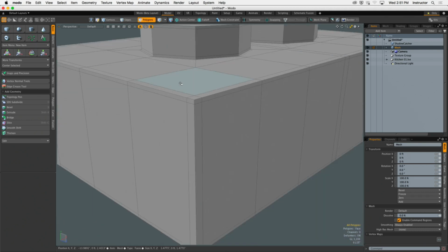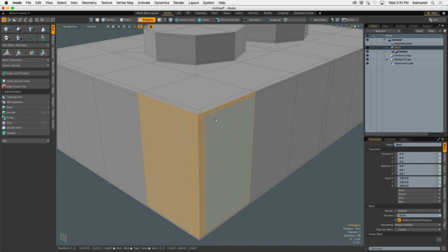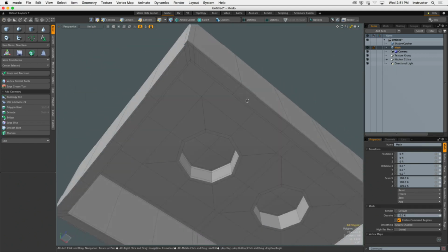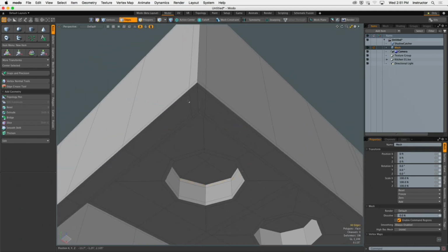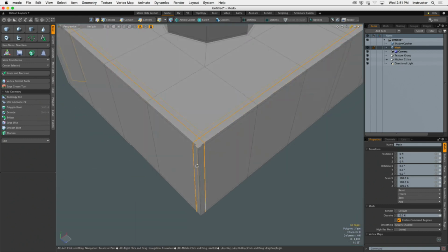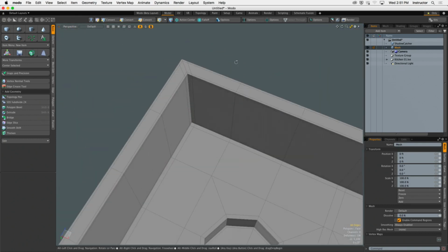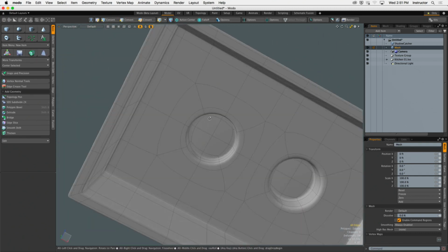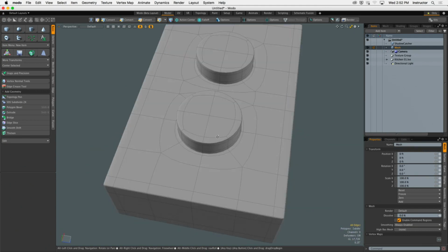Now, in the corners, I've done the exact same thing. If you think about it, I have a plane here that's transitioning to this plane over there. Well, I've added some edge loops to start locking in the algorithm and tighten everything up. And I repeat that pattern over and over again, even down into the insides. Now, in the corners, I get these cool little diagonal jobbers, which is just fine. I'm just using the loop slice for almost all of this to very quickly put in these new edge loops so that when I hit the tab key, everything is tightened up pretty closely, and I get a good high quality result.